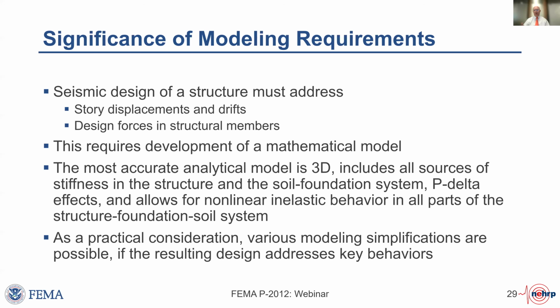We already mentioned that the most accurate analytical model would be three-dimensional. It would include all the sources of stiffness in both the structure and the foundation system. It would include P-delta effects. It would allow nonlinear inelastic behavior in the entire system so that you could, to the best of our knowledge today, identify exactly how this would perform for a given ground motion, and then maybe consider a very wide range